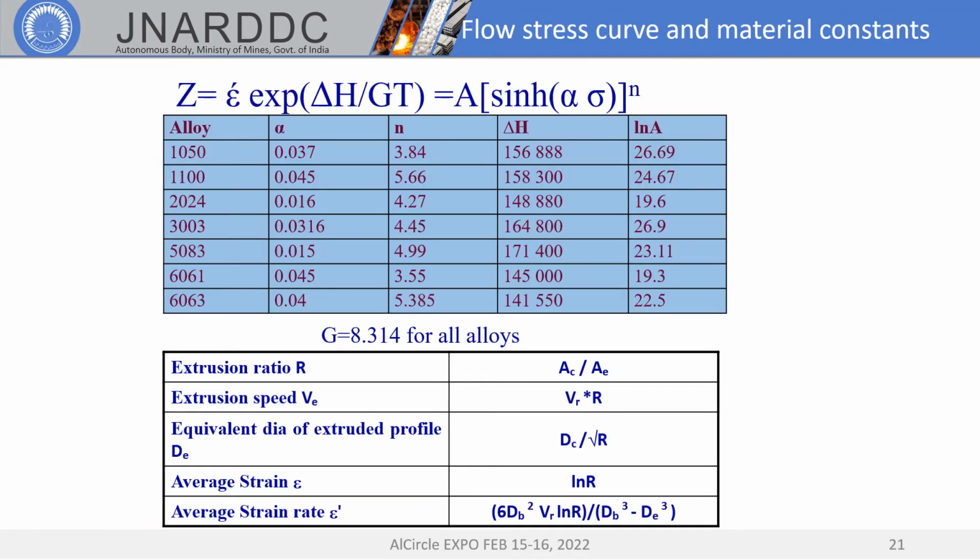Flow stress curve and material properties. The alloy deformation characteristics are mathematically represented by the flow stress curve. Using these material constants, various flow stress can be generated and relative extrudability can also be estimated. This data is very important for the numerical simulations.